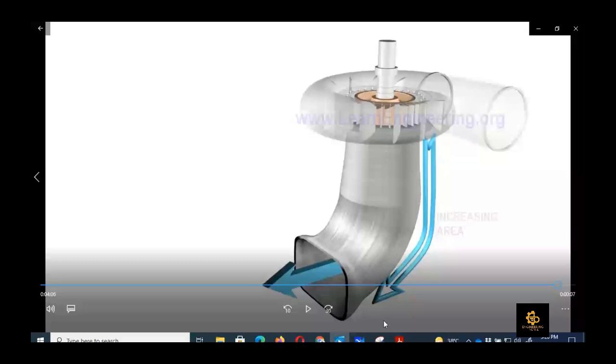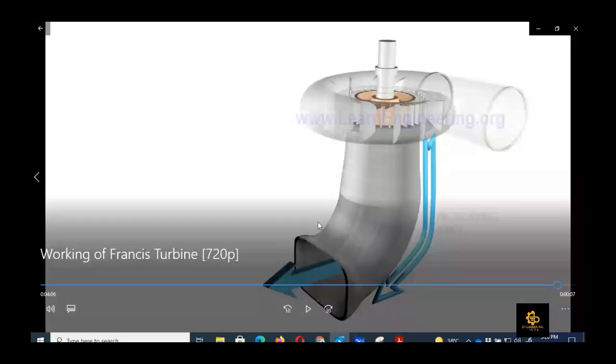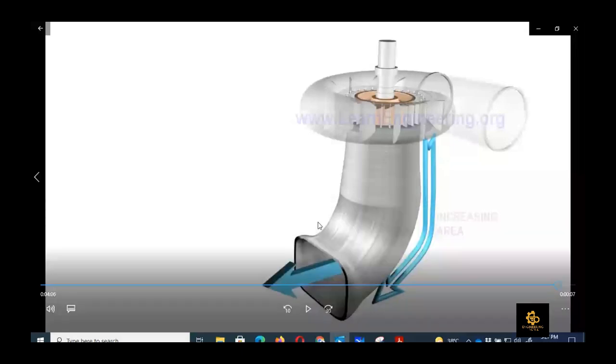And in the reaction case, the fluid loses some of its pressure energy, and that pressure energy is converted into kinetic energy of the rotor blade. So as it was shown in this video as well, there is some change in kinetic energy of the fluid as well as the pressure energy. So we can call it a 50% impulse and 50% reaction turbine. Okay, Umair Khalid?